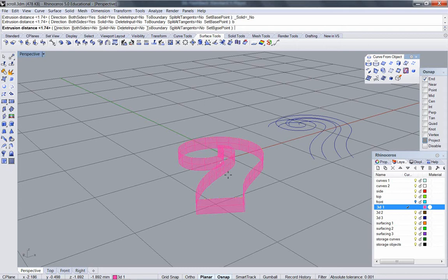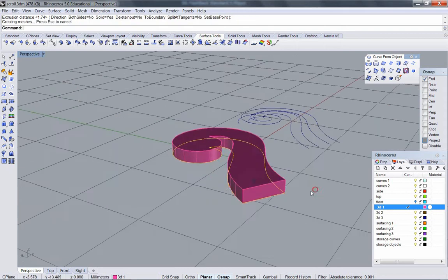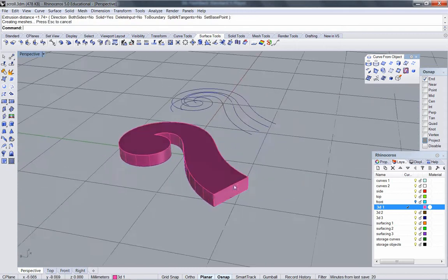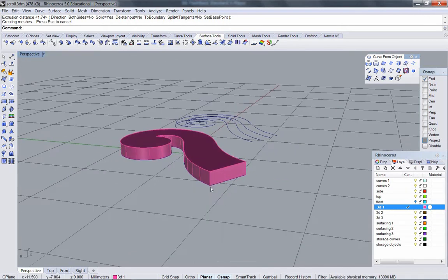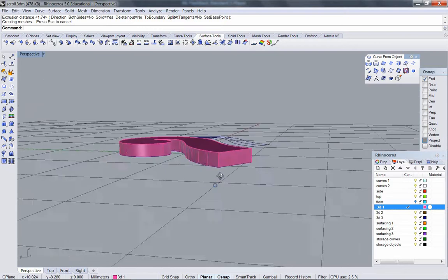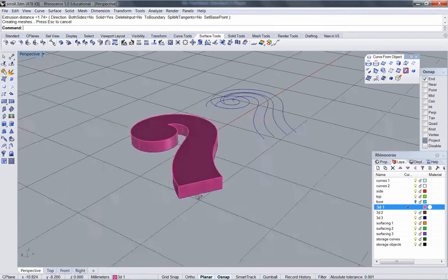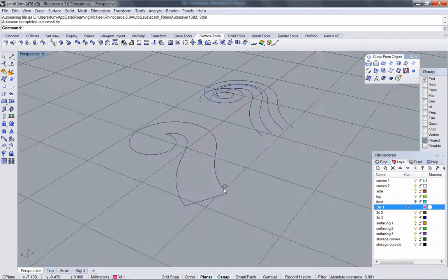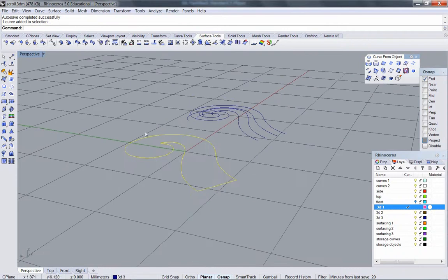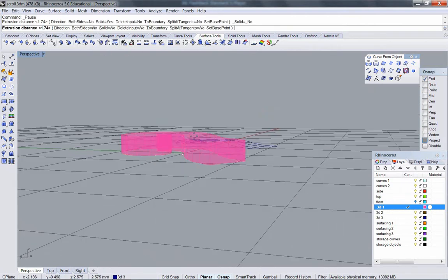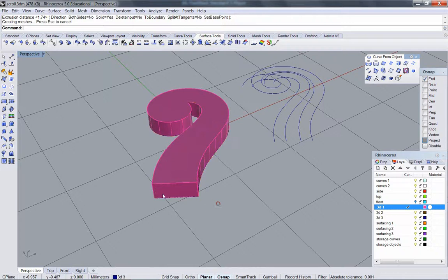Turn off both sides. Okay, so that if I did a fillet, it's going to reach as far down the side as it does over. If I set it thinner than 1.74, the fillet wouldn't be able to have enough room and it would fail. That's actually a little too low for the scroll I had in mind anyway, but it's good to know what that distance is because that's the minimum you can extrude. I'm picturing a scroll more along those lines, okay?